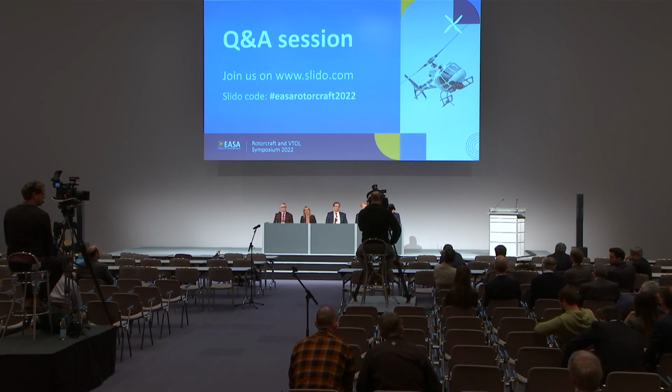So, last question for today. I see one. Yes, please. Good afternoon. Jean-Marc Sacaz, a former EASA Rotorcraft. Just a remark, not a question. To avoid any confusion, it would be better when you present your last document there to talk about height. I know you are talking about radio altimeter. Probably the wording is not the best. Talk about the height, please, and not the altitude. Because at different times you mention altitude, and as soon as we talk radio altimeter, it's better to talk about the height over the ground. Thank you.